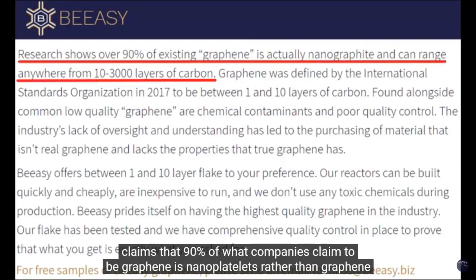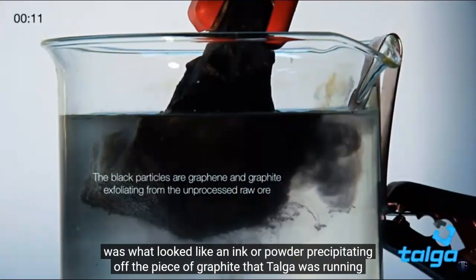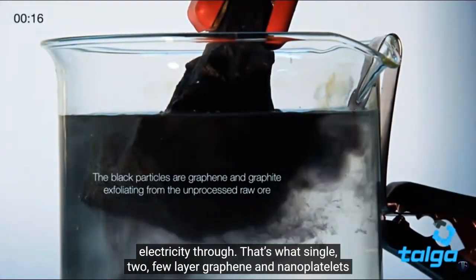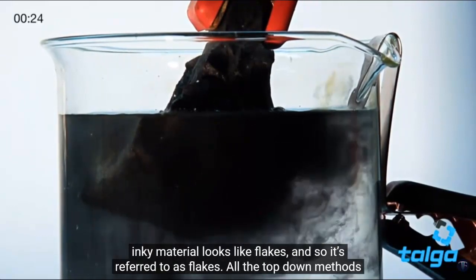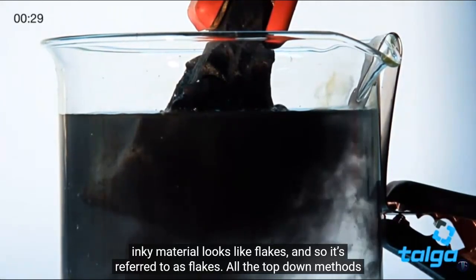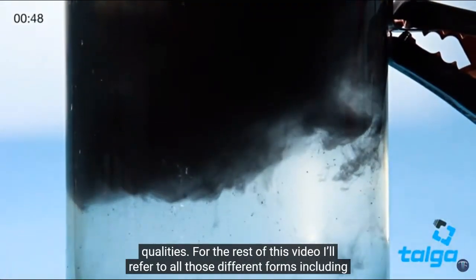What do I mean by flake? In this video, there was what looked like an ink or powder precipitating off the piece of graphite that Tolga was running electricity through. That's what single, two, few-layer graphene and nanoplatelets exfoliated from the graphite look like to the naked eye. At the microscopic level, that inky material looks like flakes, and so it's referred to as flakes. All the top-down methods covered in this video produce graphene and nanoplatelet flake in different ratios and qualities. For the rest of this video, I'll refer to all those different forms, including nanoplatelets, as simply graphene flake.